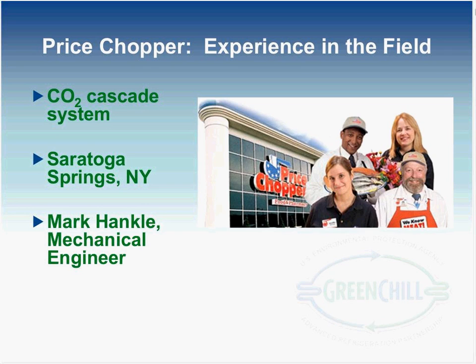There are challenges. I'll go first, Travis. With transcritical systems, the pressures, like John Baird mentioned earlier, are a lot higher. You're talking about 1,400 pounds of discharge pressure. The advantage, though, is that you have a total natural system. There are no HFCs or HFOs in the future. No chemical refrigerants are required for the system, so that would be an edge.